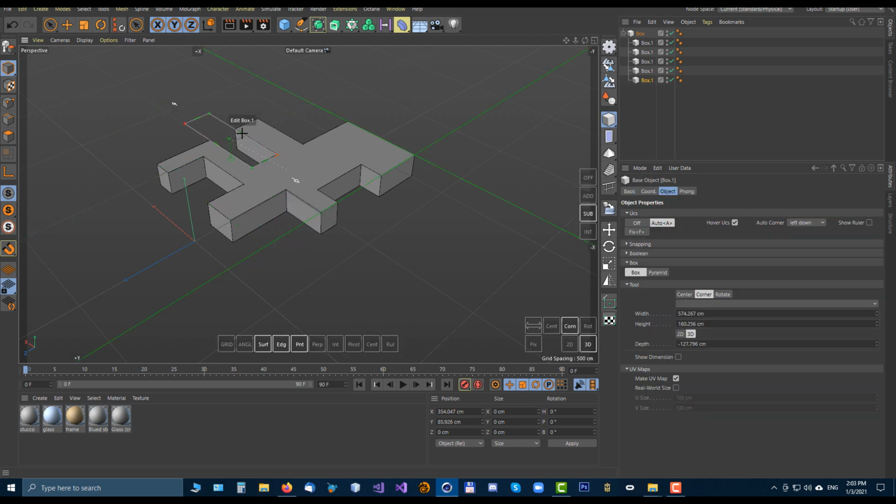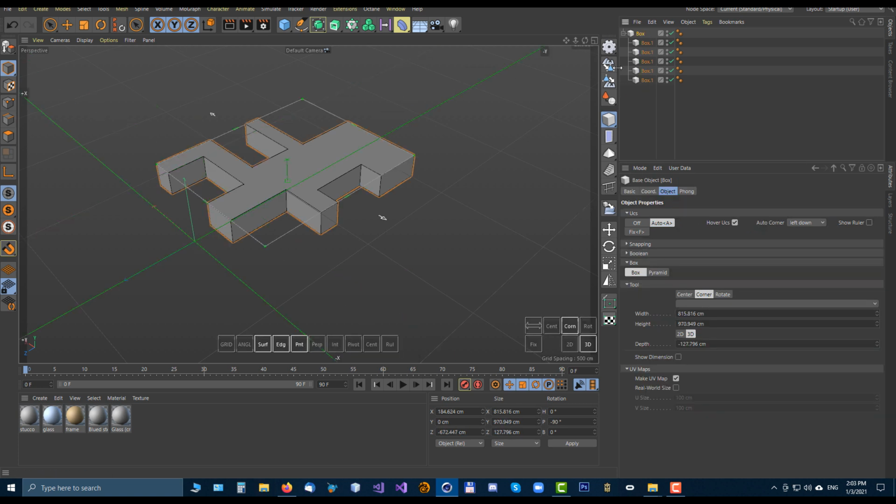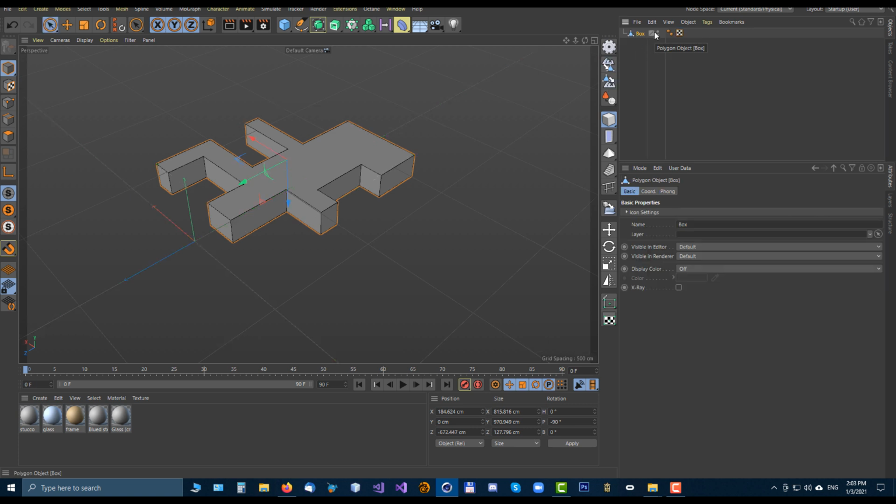This is a very nice example of a parent modifier, and if you freeze or convert these objects into polygons, all child modifiers which are not generating geometry themselves are deleted, and only the box which is modified remains.